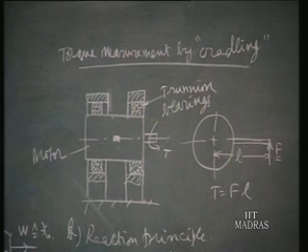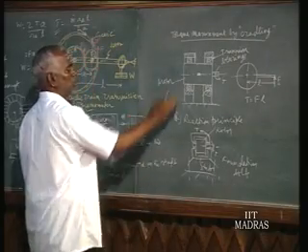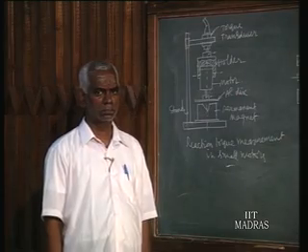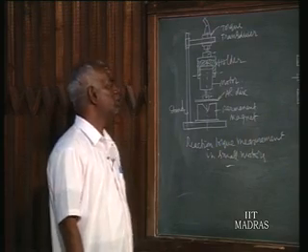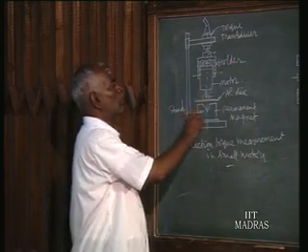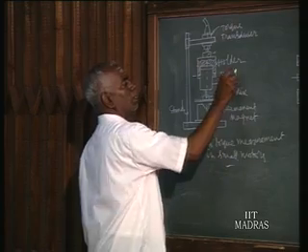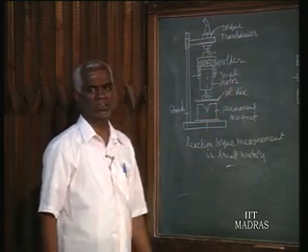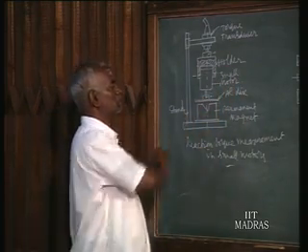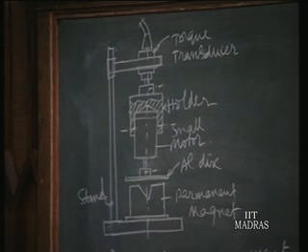So according to this relation, we can measure the torque by measuring the force. So this is one method. Now the second method is in case of small motors, say a small motor of a few watts, 10 watts capacity, where the weight will be a few grams, say 100 to 150 grams. In such cases the reaction measurement can be used comfortably to find the torque developed in the motor.